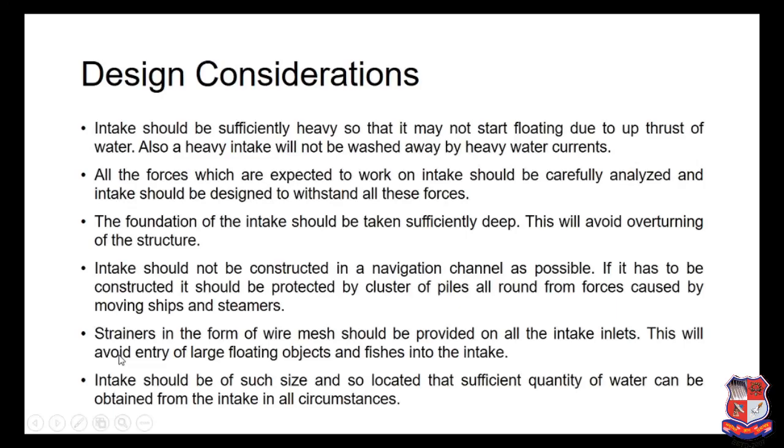As we have discussed, we are providing strainers, or we can say screens, in the form of wire mesh, at the intake only. This will avoid entry of large floating objects and fishes into the intake.